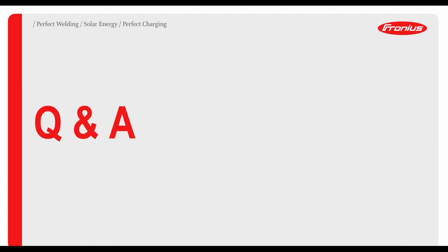Then, how would a power diverter affect the switch off of the export limit? Depending on which power diverter, let's say if you're using a third party one, I'm not sure, like a catch power or something. If you're using one of those, then they've got a separate CT, so they have to see a certain amount of export. However, they're not under the control. So how that works with the system, I'm guessing that they probably wouldn't work in these systems.